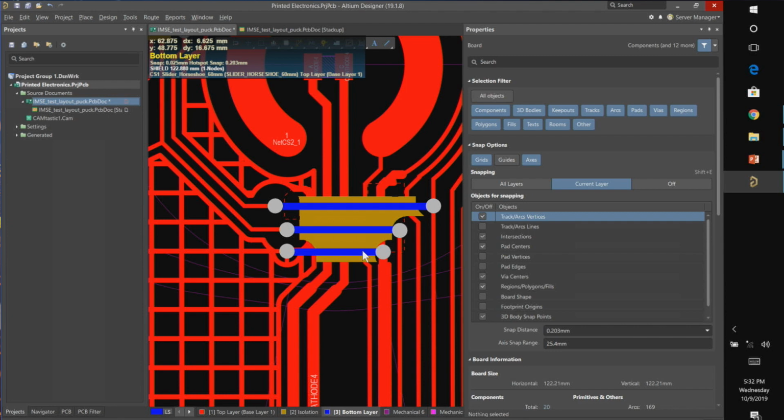Is that top layer going to be printed with silver? A conductive ink. Yep. Silver migration, that I'm not too familiar with the materials that they're using. You use things like alternate polarities so you don't get silver migration through the layer. Through chemistry, I know the conductive inks, that's a pretty new field. They are probably developing that, but I believe they have it perfected to a level which is certainly catching on in automotive. So they're running with this.